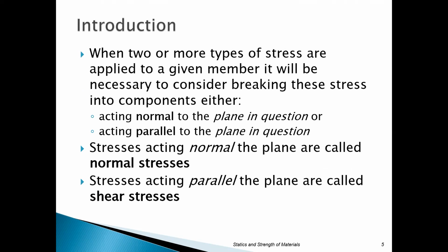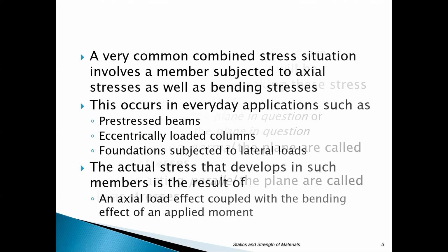That's another term we've been using, axial stress. That's simply your P over A kind of formula. That's what we talked about primarily in chapter 8. Now we also talked about shear stresses, which are the stresses that act parallel to the plane. Those are also P over A, but when you're dealing with bending, it becomes a little different. We'll look at those here in a sec.